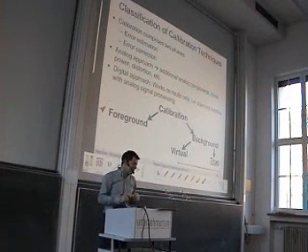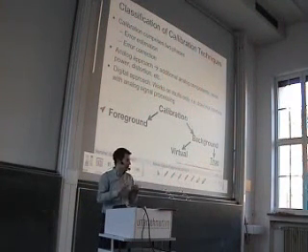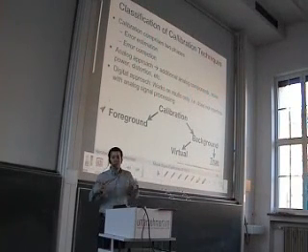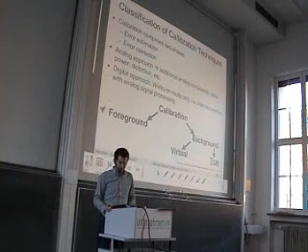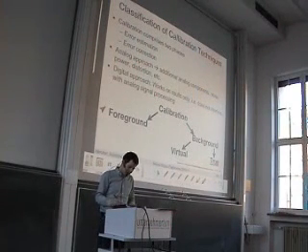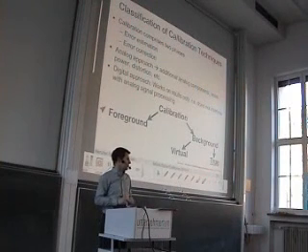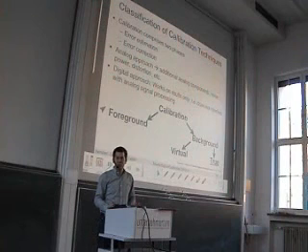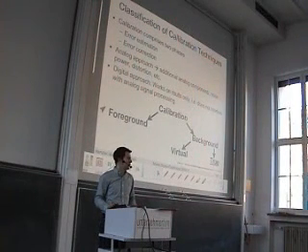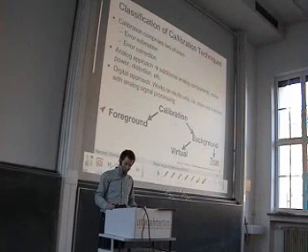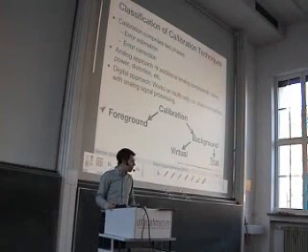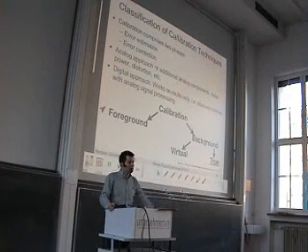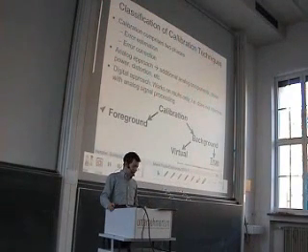And it also requires some means of switching circuit blocks to take one out, put another one in, and so on. So this is also some more effort. So the desirable way is always to have a true background calibration. This is the goal. Well, it's not always achievable, but if you find a tricky solution to have it in the background, in a true background way, then this is very advantageous because then you can react all the time without the need for additional elements.